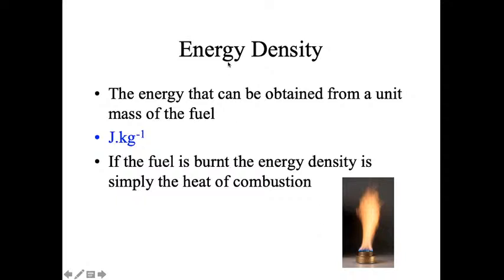All right, another new piece of information for you. We got energy density. And just like Sankey diagrams, it's not overly complicated. Just like energy degradation, it's self-explanatory. It's right in the name. Energy density is how dense the energy of our source is. So how much energy can be obtained from a unit mass of the fuel. Just like density is mass per volume, this is our energy per mass. So if the fuel is burnt, the energy density is simply the heat of combustion. That's kind of our simplest way to determine energy density.